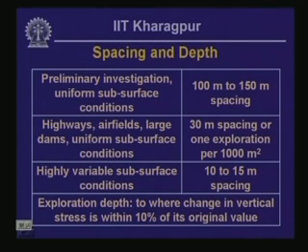It is quite obvious that if the investigation is for deciding the preliminary alignment of a linear facility such as a highway or a railway, then the investigation can be carried out at a relatively wider spacing in comparison with an investigation undertaken for the detailed design project of the same facility.